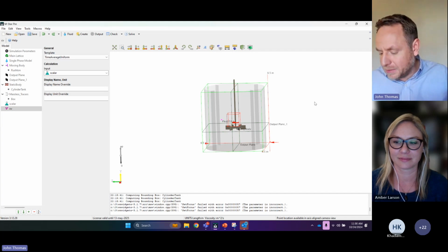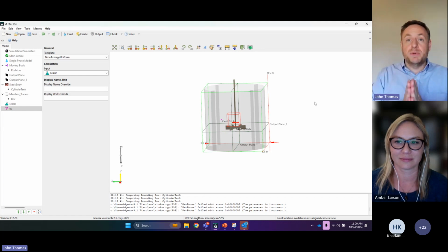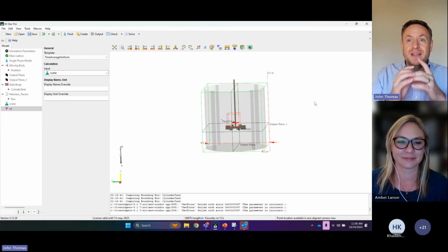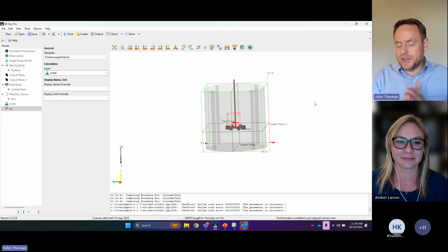Different GPU cards impact simulation time and size. Very simple rule: more CUDA cores, faster runtime. Period. More GPU RAM, larger simulation. That's the answer.